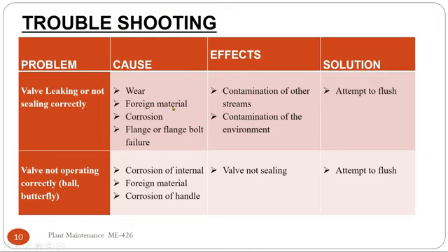maybe if there is no filtration system, or the filters or the strainer installed on the pump, on the line or on the supply system is not working properly, or the filter size is large, or the pore size in the filter is large, so the foreign material will come. Foreign material may include dust, dirt, debris, or any other thing.